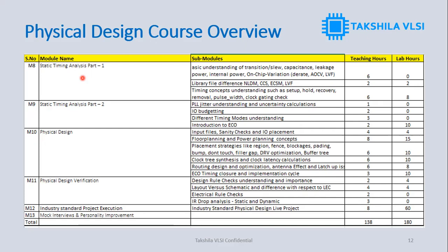See, in your design you will have some standard cells and macros, or the logic cells. Fine. So for those particular logic cells, there should be some delay. So in the .lib file, the library file, all the delay values are mentioned. That standard cell or macro needs some modeling technique to define how much the delay is.